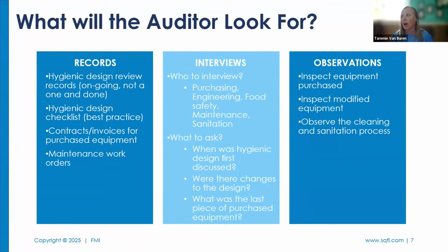Interviews, who are you going to talk to? The auditors are going to want to talk to everybody. Purchasing should be aware of the hygienic design requirements. Engineering, who's probably assisting on the design of the equipment. Food safety, for sure. We want to know about it, right? Maintenance, sanitation, all those people should be aware of those principles. I should be able to go to a maintenance guy and ask him, what kind of welds are you doing? What do you look for to make sure you've got a good weld?